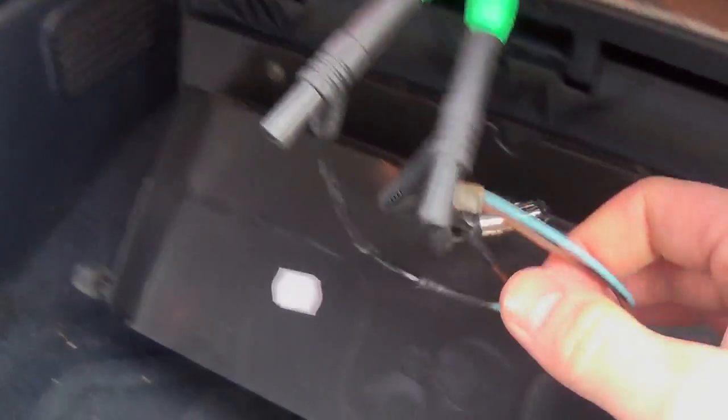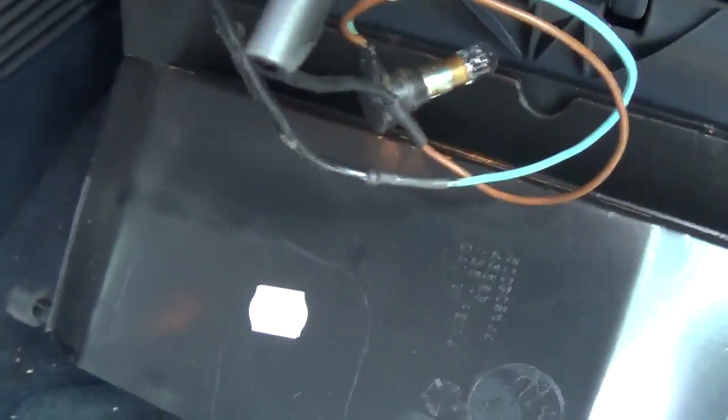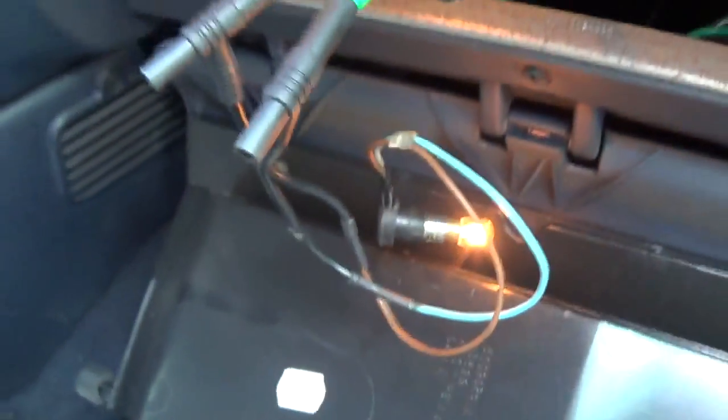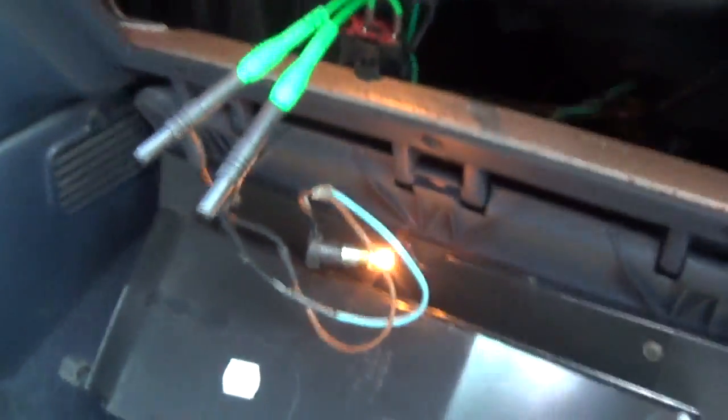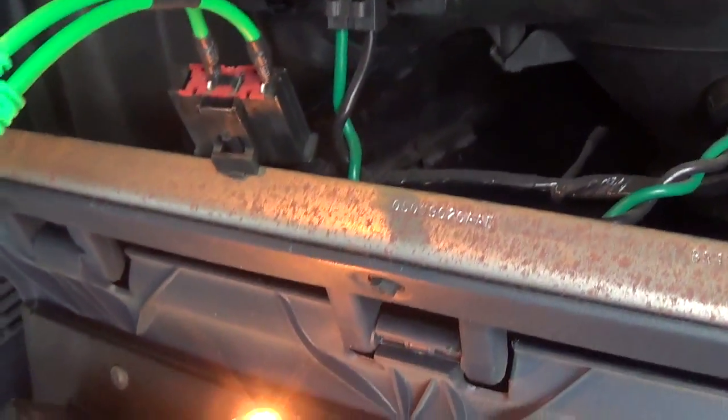Alright, I have my new and improved test light connected across the power and ground. So let's turn the key on. We have a feed. Excellent. So our relay works. Now we also want to check this when it's plugged in, because maybe the test light's not bright enough, or should we use a load pro? I don't know. So let me plug this back in and back probe this. Alright, now we have it plugged in and back probed with our light in place. Turn the key on.